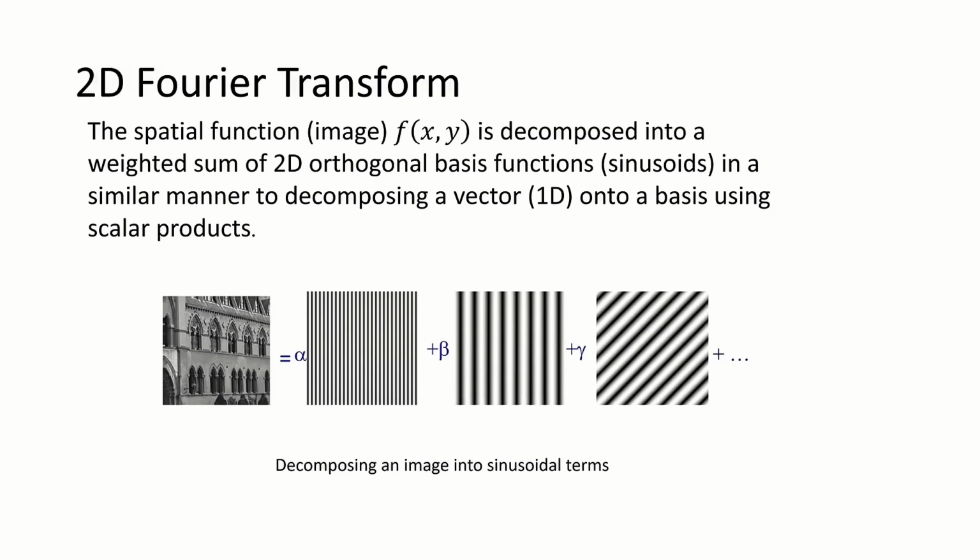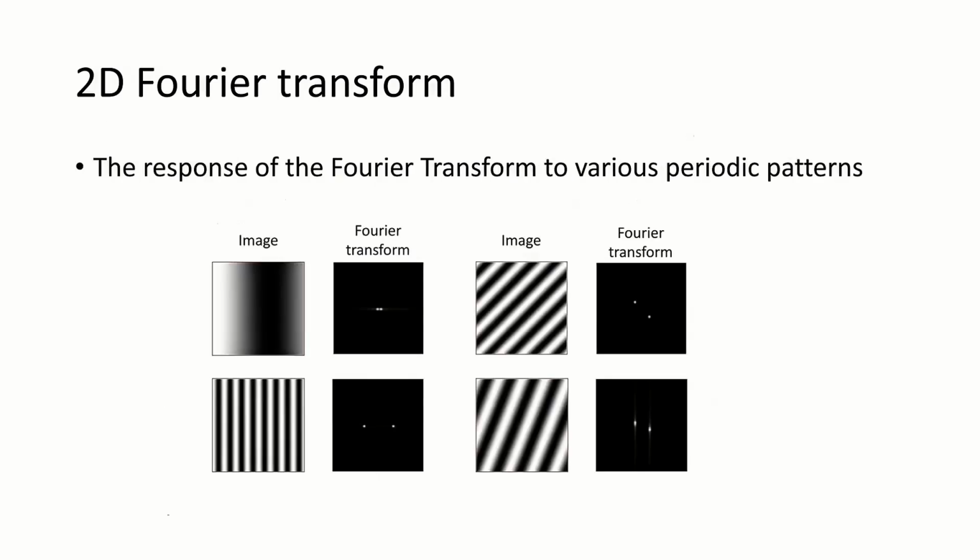So the only difference between the wavelet transform and the Fourier transform is this basis function. I am decomposing any signal or image either into a sum of sinusoids or a sum of wavelets. This is the difference, nothing else. So if you understand the Fourier transform, you can understand wavelets easily. This is a very complex image, and I decompose it into various components with some weights. But let's say we talk about a very simple image like this one, where white means high and black means low.